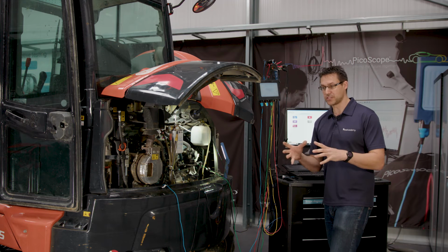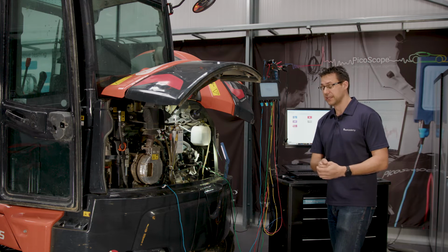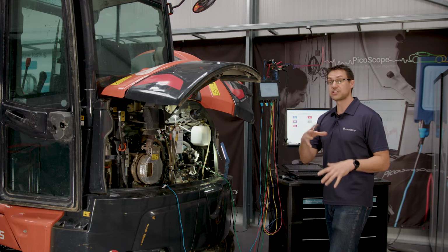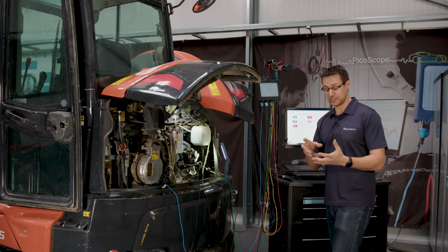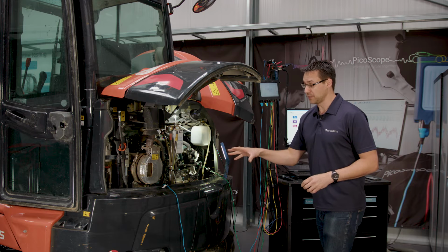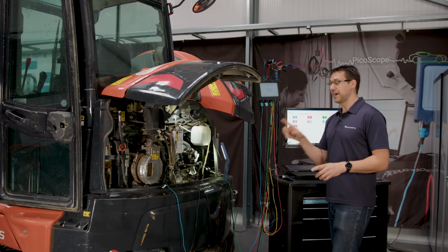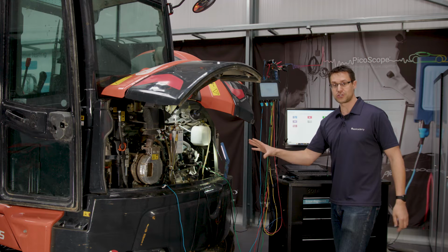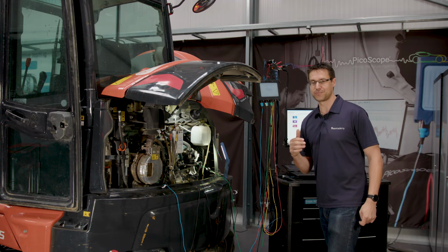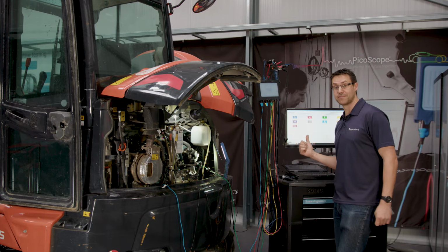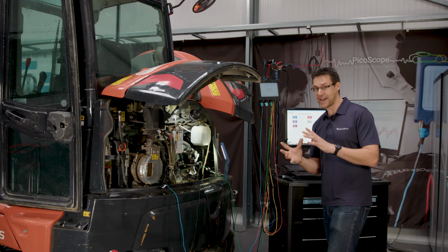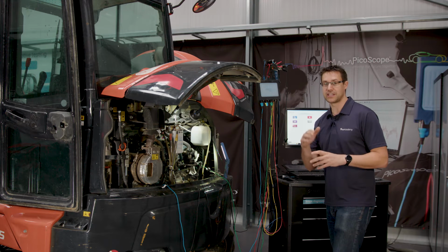So this is kind of how misfire detection works inside the ECU. It looks at the speed or the rate of change in the crankshaft sensor to determine how each cylinder is contributing to crankshaft speed. So we're going to use that. That maths channel is a built-in maths channel. However, with a lot of construction and plant machinery, they set their idle speed slightly higher than what the idle speed is in the crank sensor built-in maths channel. What we'll do is I'll quickly show you how to reform that and actually get a change in the output.